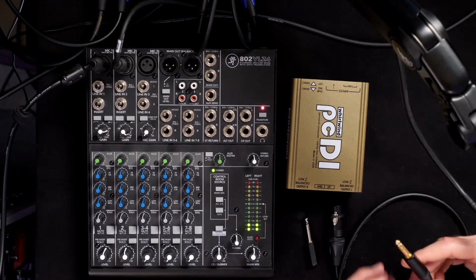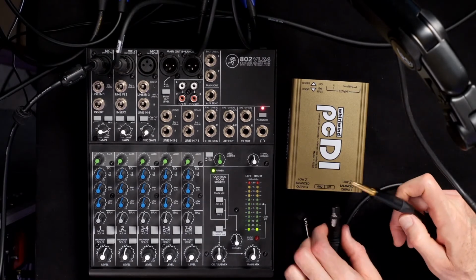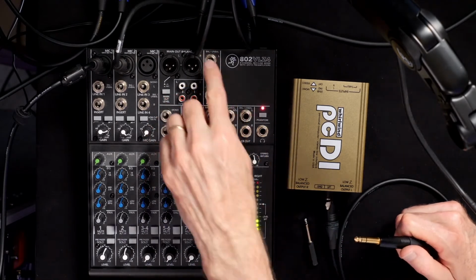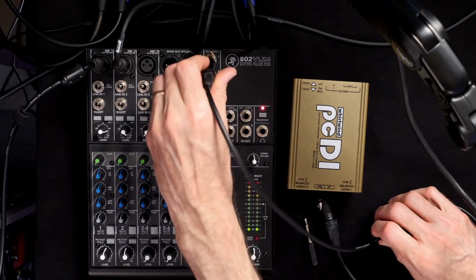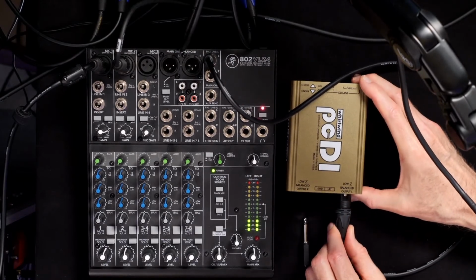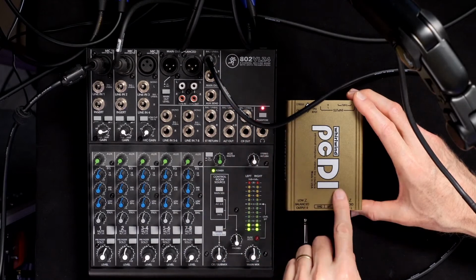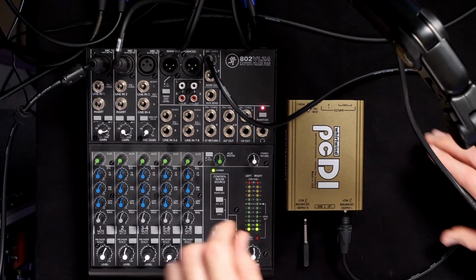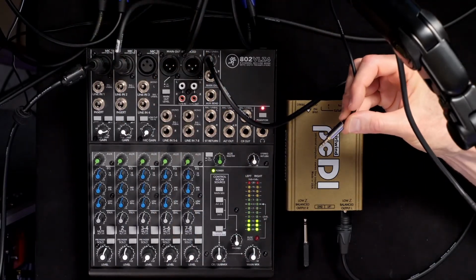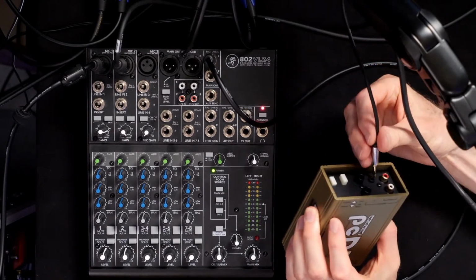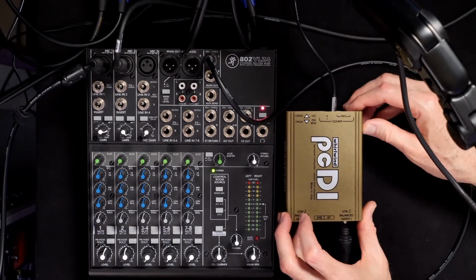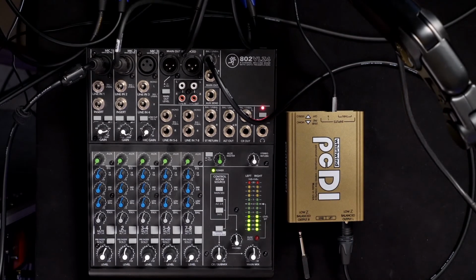In this case, I have a 1/4-inch TRS to female XLR, and it so happens that I have a balanced 1/4-inch TRS output here, so I can connect this here and then connect this into one of the outputs. So now I'm feeding the output from the mixing board backwards into the DI. And then let's just get a 3.5 millimeter TRS connector that's going to go into our ATEM Mini. Okay, we have that now. All right, let's switch over to that and see how that sounds.